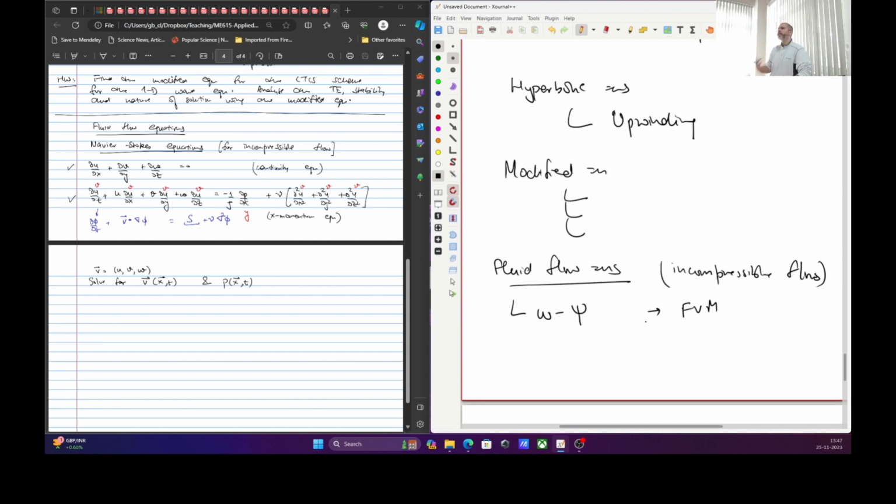because there's no natural boundary condition for omega or psi. Natural, not mathematically, but natural like intuitively. Because we had to come up with ways to get boundary conditions for omega and psi using omega written in terms of psi and so on, especially on the walls. It was quite problematic, and that in fact is the reason why we do not work with these variables.